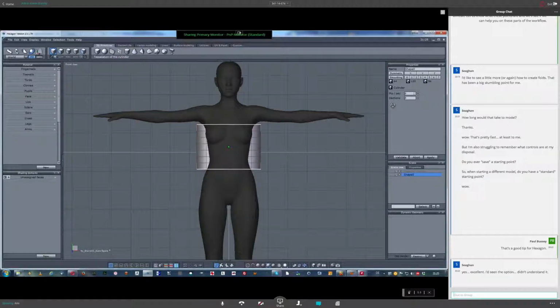And then you see here in the side menu points or sections in numbers and parts sections, and then the sections. So I'm taking this down to 6 and this down to, I want a very rough cylinder, to 4. Now why I choose 6 and 4, that's simple. I want a very rough, a very low poly cylinder, which makes it easy for me to deform and position. The more polygons I have, the more I have to work to adjust the shape. So I will add more polygons later when I use subdivision.